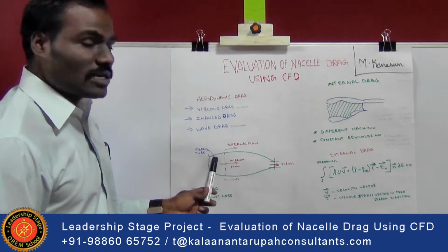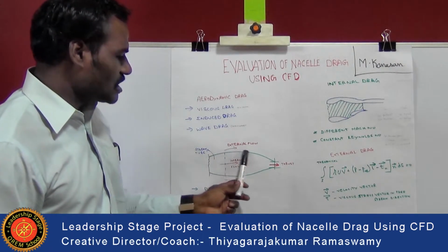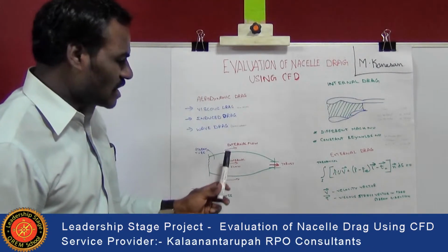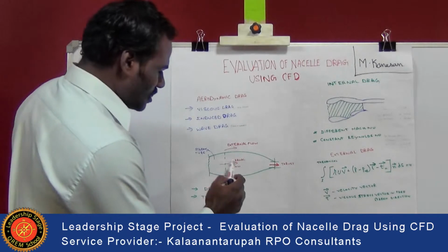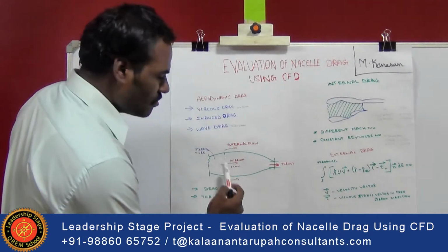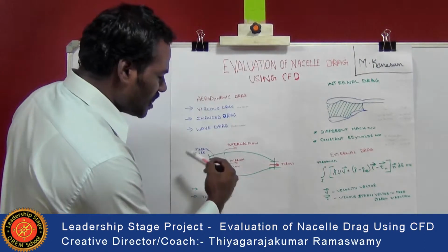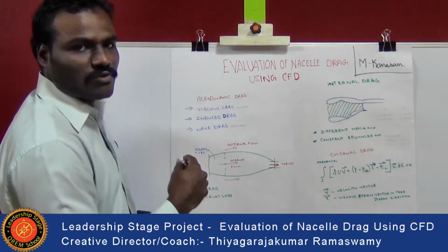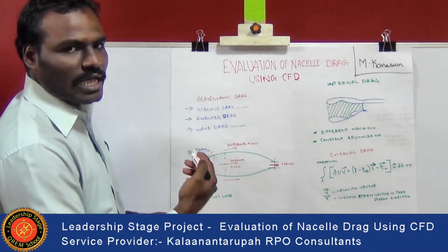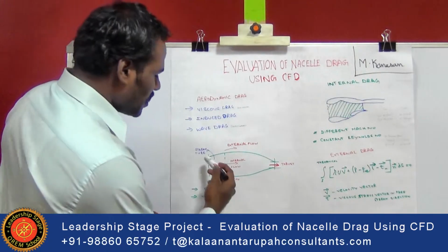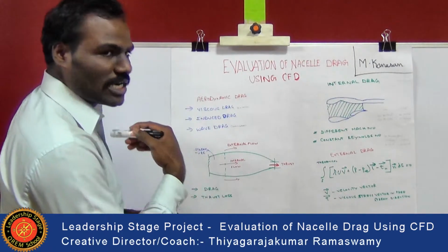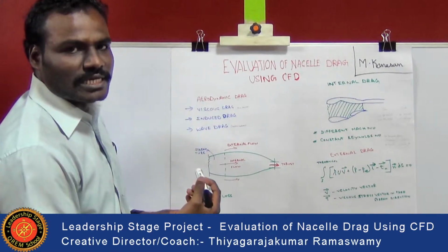Here the graphical representation of a nacelle is shown with respect to the internal as well as the external flow. The flow going inside the nacelle structure is known as the internal flow. The fan absorbs the air from the nacelle lip. There is a split in the nacelle structure which helps in splitting the air being extracted inside the engine.